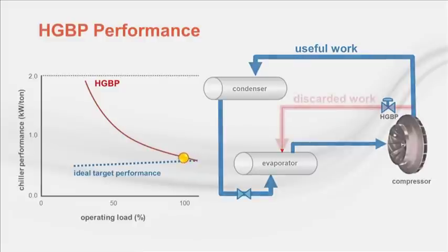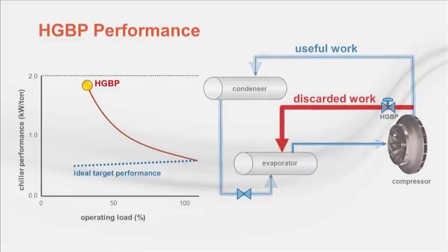As the amount of bypass gas increases, the capacity or tons of cooling goes down. With the compressor flow and work remaining nearly constant, the input power per unit of refrigeration capacity, or kW per ton, goes up dramatically. ASHRAE 90.1 caps the amount of hot gas bypass to 10% of the compressor capacity. In practice, it is a good idea to avoid the use of hot gas bypass entirely unless dictated by a need for extremely low unit capacity modulation.